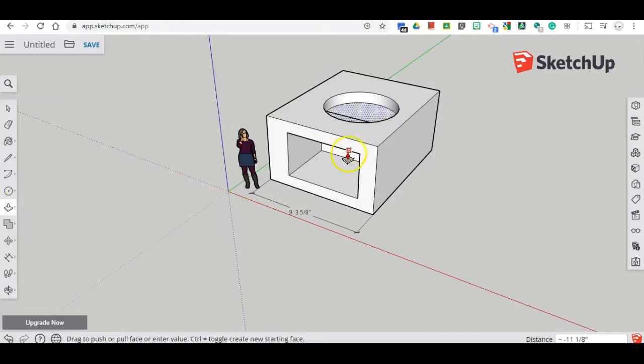Click on that surface and drag it to that face. Oh, interesting, it made it like a solid. I wonder if there's an undo button. Control Z should work. Yep, Control Z works. So Control Z is undo. And you can click and drag that up to make a cylinder.